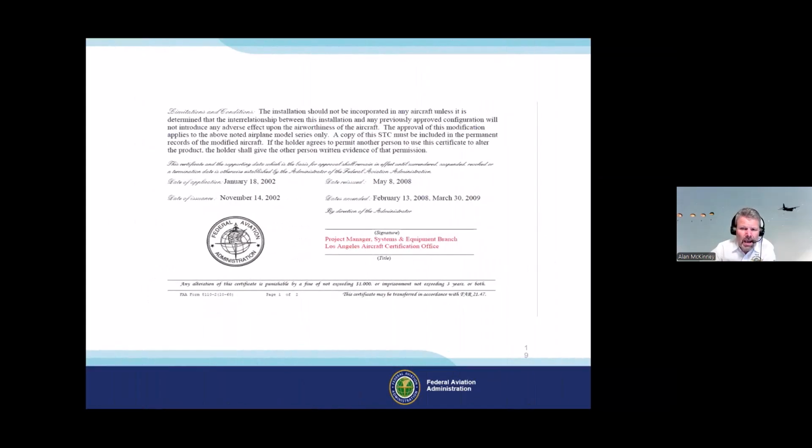So that was the top half of the STC certificate. Here's the lower half. So if you see this in the records, you need to put a little flag, a little check mark of here's something I have to address. This STC certificate was not purchased legally because there's no ACO signature. And that's by design. This was printed off of FAA.gov, and the reason that's done is so that folks don't go in there and just print copies off and say, oh, I purchased it legally.